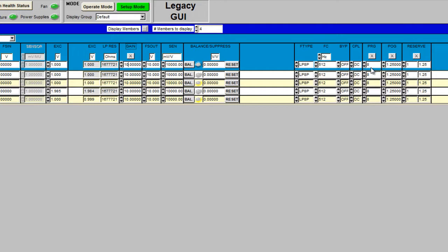An example of this is the in-band signal from an accelerometer and the accelerometer's out-band resonance. The out-band resonance could be much larger than the in-band signal of interest. By using a distributed gain topology, the only part of the amplification that is applied to the in-band signal is the pre and post gain. The out-band signal is only amplified by the pre-filter gain and is removed before additional amplification is applied.